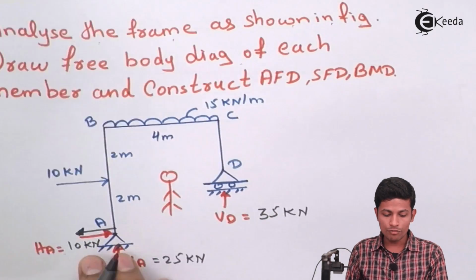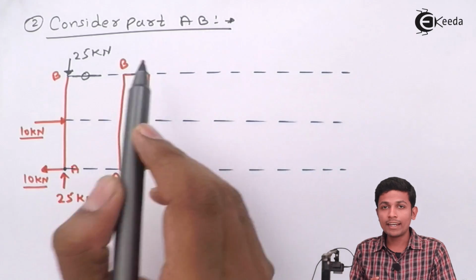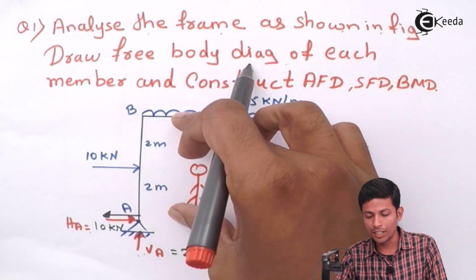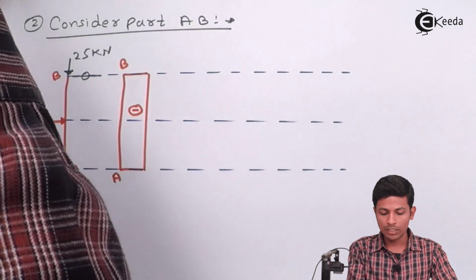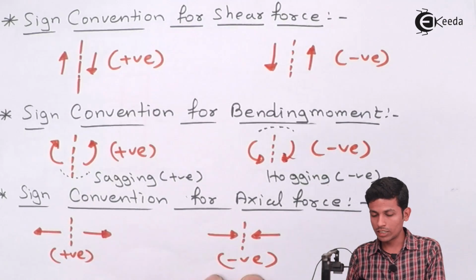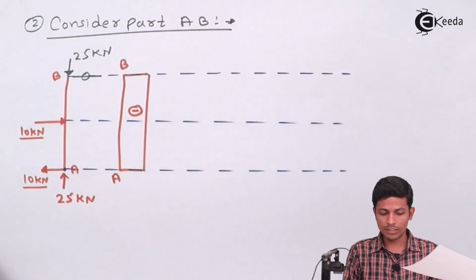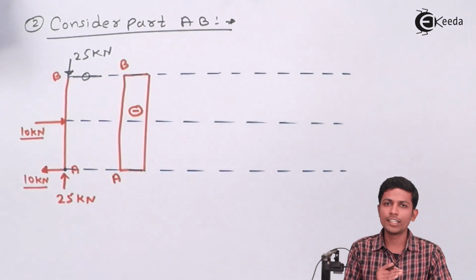So we got the value of this compression, this will be minus, so we will draw the minus inside the frame. See, we are drawing the FD inside the frame, it will become here. Okay, so we are drawing like this. This is minus because our value will be minus. See, this is compression, this is minus, this is tension, so plus. Okay, remember this first thing: negative sign draw inside the frame, positive sign draw outside the frame.